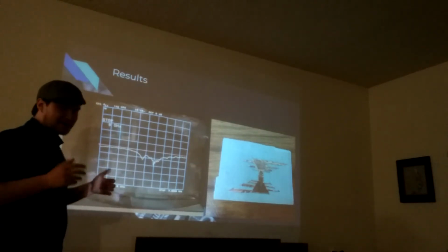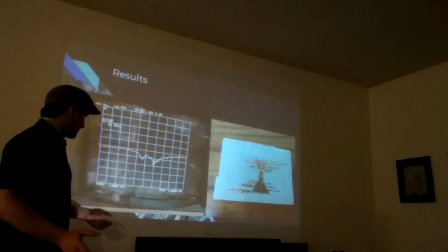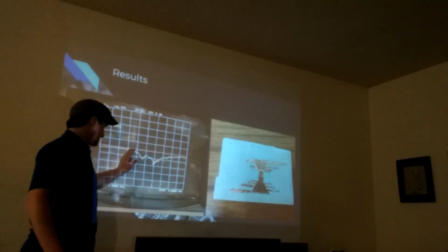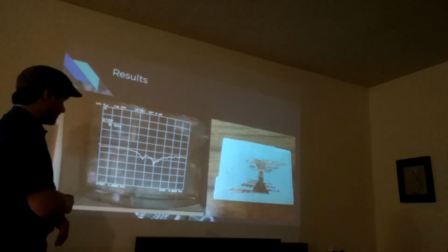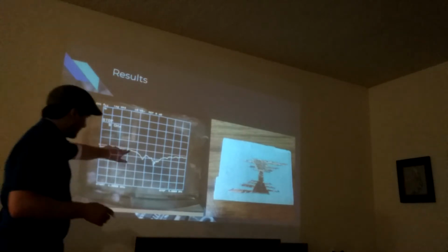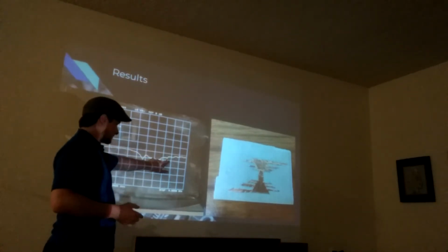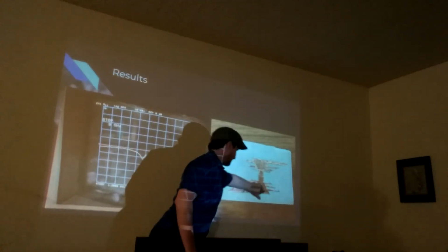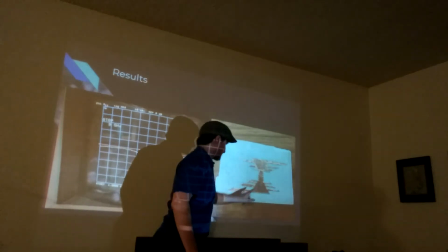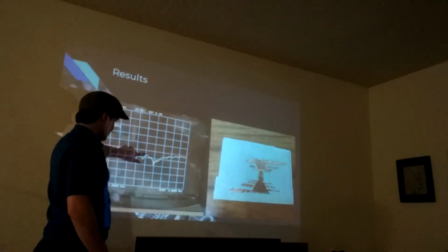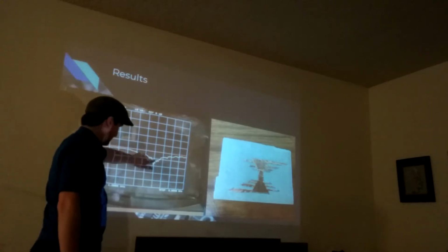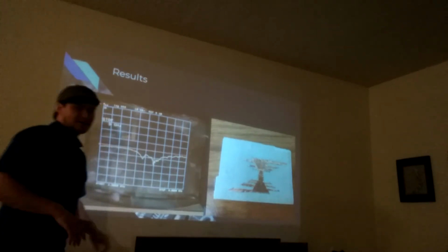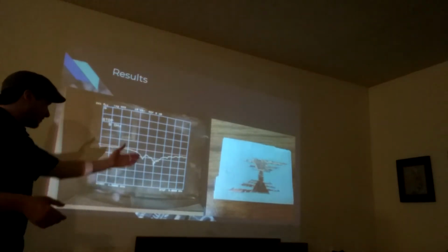What I noticed is it had kind of the same properties I was looking for, where it would be good over a wide range. In this case, it was from 4 gigahertz up to 8 gigahertz. However, it had a couple divots that I was kind of expecting if this was a bunch of patches together, where this is one patch, this is another patch, this is the next patch, and so on up the ladder. And you see these spikes, another spike, another spike, and another spike as you go up in frequency, which I think is due to the dielectric constant of the material I chose.